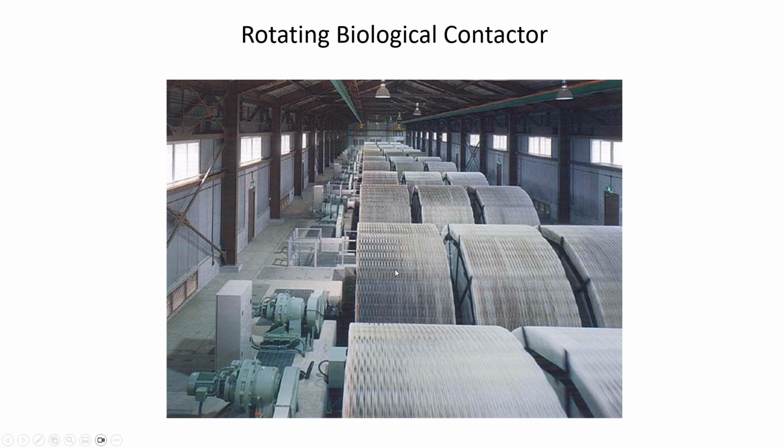They're getting exposed to air, they're getting exposed to substrate when they're dipped down into the water, and what they'll do is that a slime layer will grow on this, and eventually it will slough off. When it becomes too thick and too heavy, then it'll fall into the water, and that's good because that's what we want. We want it to turn the dissolved BOD into something that will settle, because dissolved BOD won't settle. It's in solution, whereas the cellular material, like the slime that sloughs off of an RBC, can be settled